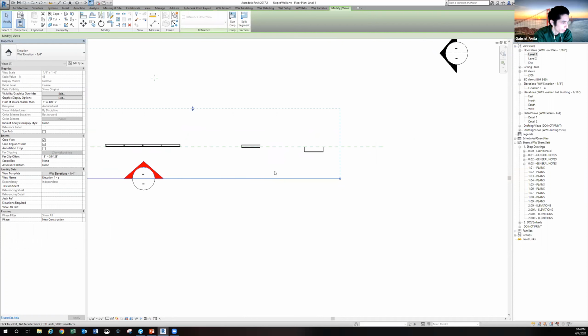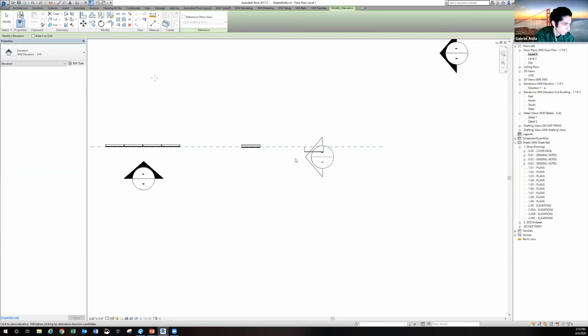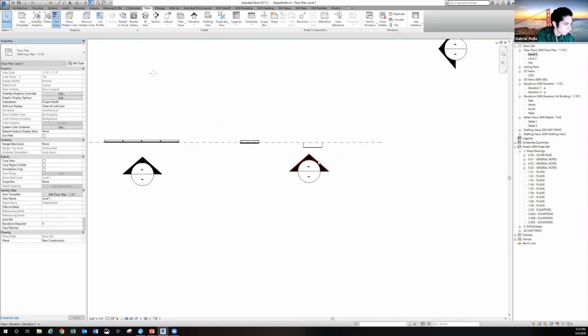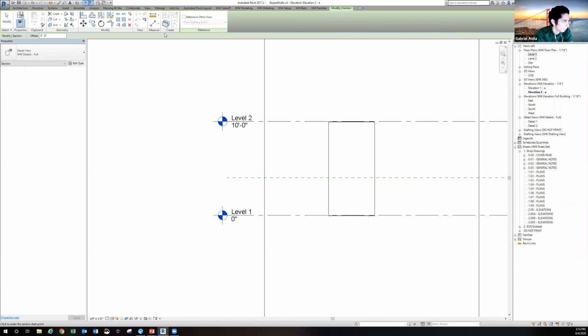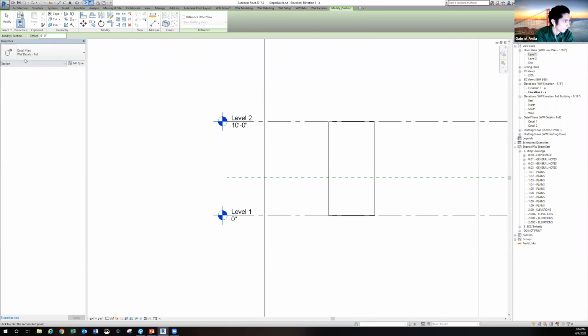So we created a view. For those of you that want to create a view, you go to View, Elevation, and for some reason it doesn't want to pick up the sloped wall. You just hit Tab, and then it'll rotate it, and then you can click, and that'll create a new elevation for you. Now this is my elevation, and then I would just create a little section using, sorry, I'm going fast, View, Section, and use the WW detail tool, and just cut a section through here.